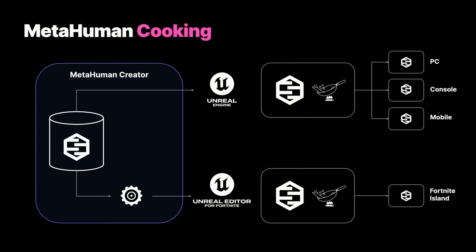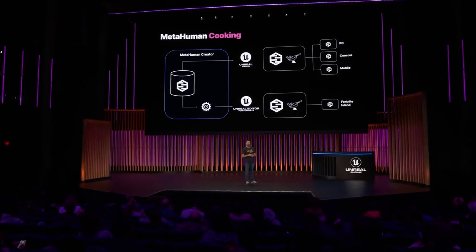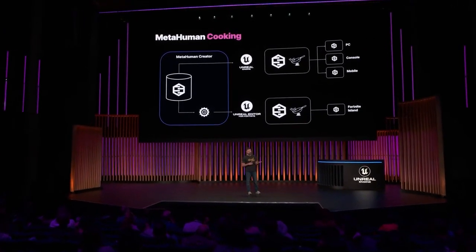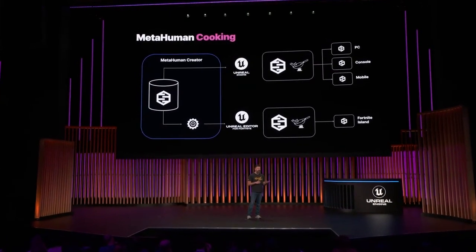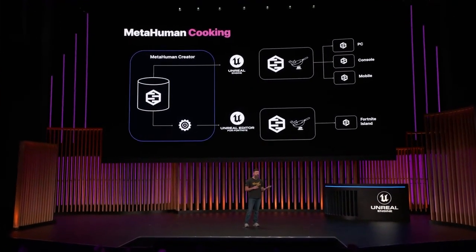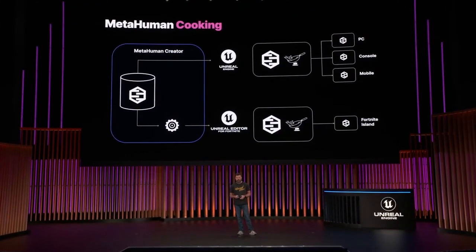With an Unreal MetaHuman, you have the option to cook what and however you want, giving you complete control over the entire end-to-end process. For UEFN, we have chosen to pre-process assets and made decisions for you that make the most sense for working in UEFN. You have fewer decisions on how that character is processed, but the benefit is your asset is already in a great place for cooking into UEFN scenarios.